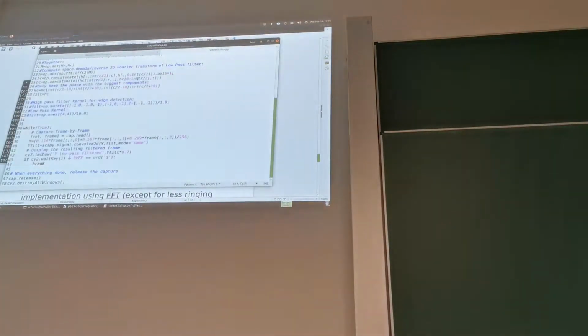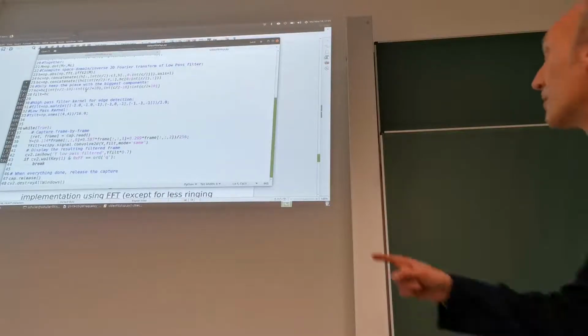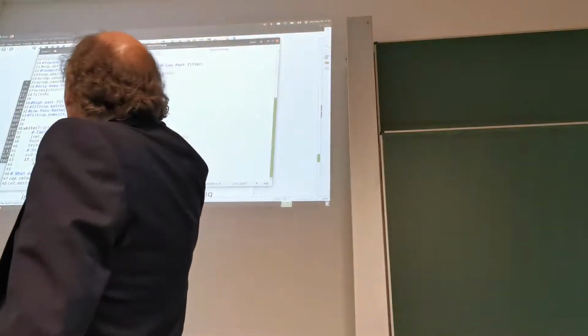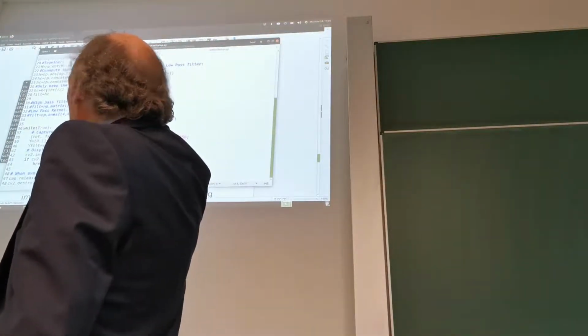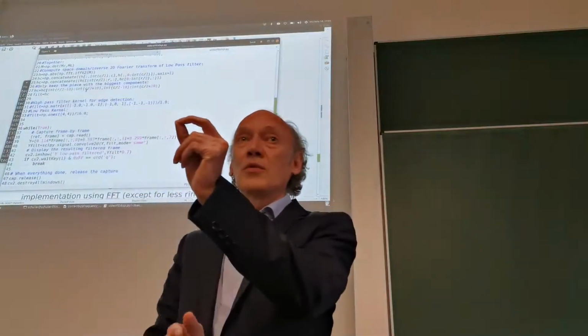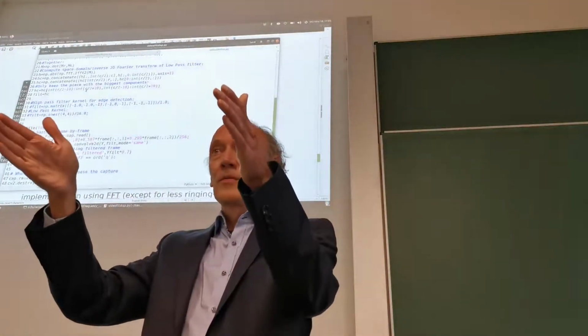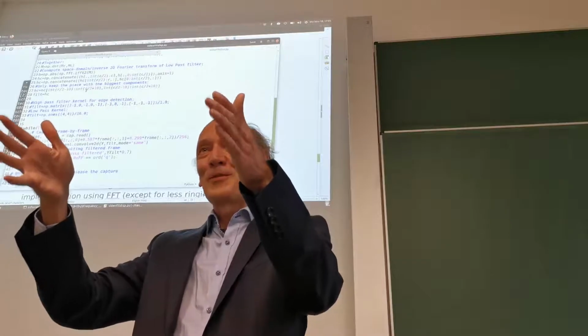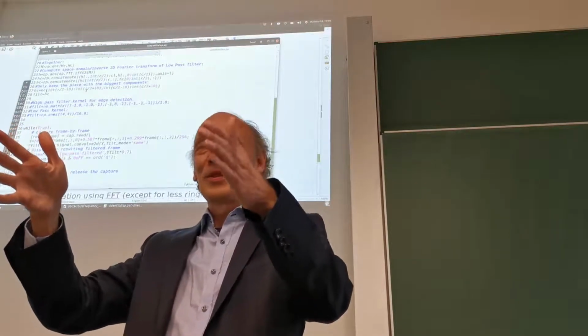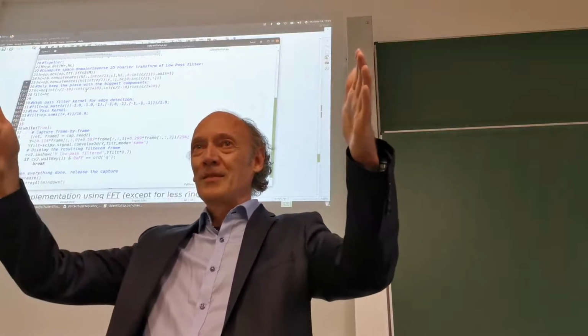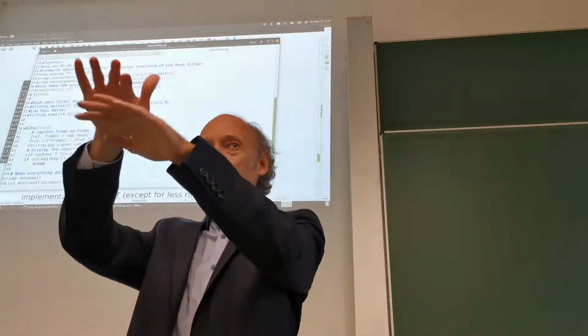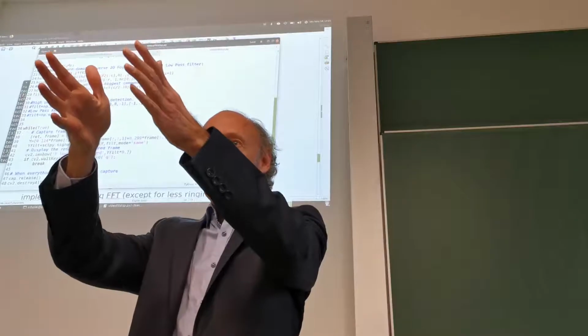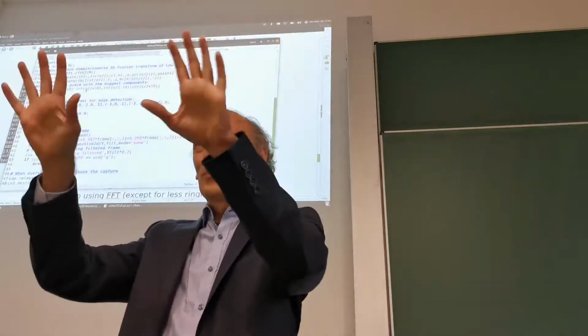And when we look at the program here, we can see that we only take plus minus 10 coefficients. Right? Here you can see r over 2 minus 10, r over 2 plus 10. So that's basically the center of our sinc function, plus minus 10. So it's quite a lot of cutting, right? When you imagine that the original impulse response was 640 by 480, and what you keep is actually a small 10 by 10 center. So most of the ripples we actually threw away.